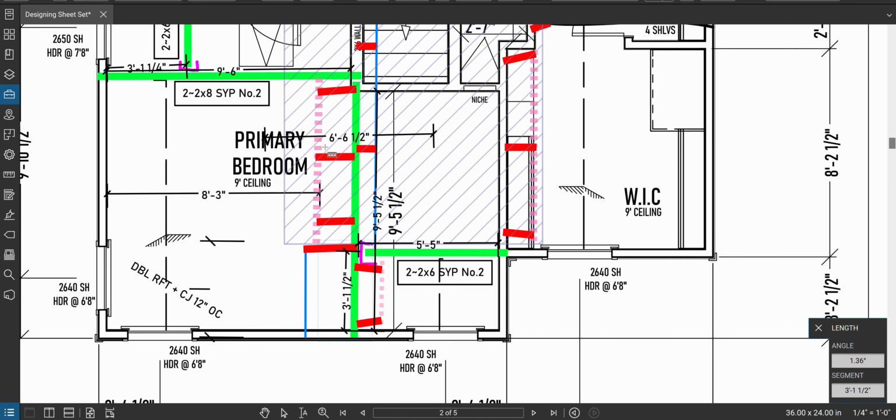Okay, so we're dealing with these 2 ridges here. So we'll go back to here. All right, here's the blue ridge, here's the blue ridge. So on average, what's happening here? This ridge is being supported from here down to that purlin line. This one's supported from here to this purlin, but the purlin's also sitting on the beam.